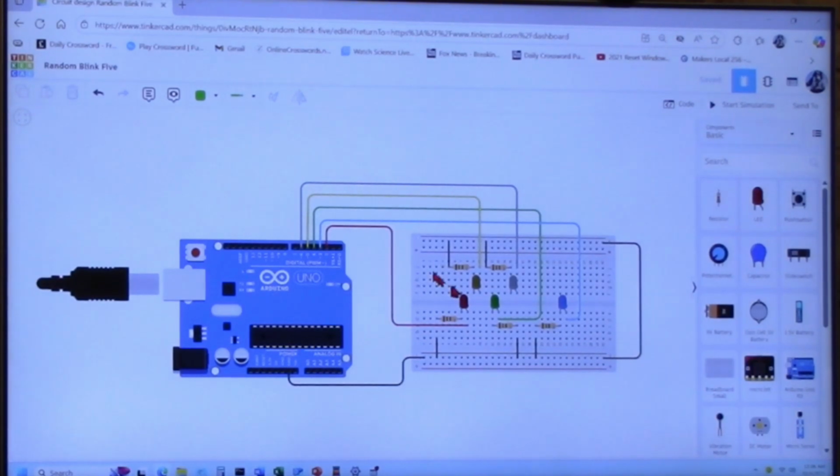They're getting full power. There's nothing in here. There's no analog input for pulse width modulation, right? So all of these outputs here, 2, 3, 4, 5, 6, are bang, 5 volts on, that's it. Or this is just but using the random function. So this is our last piece that we need.